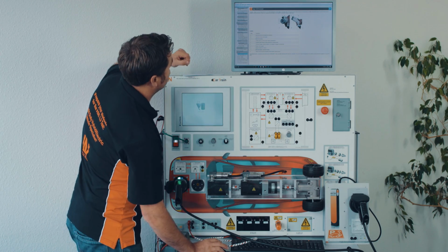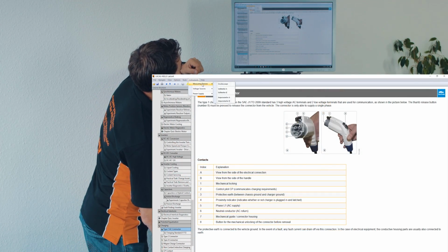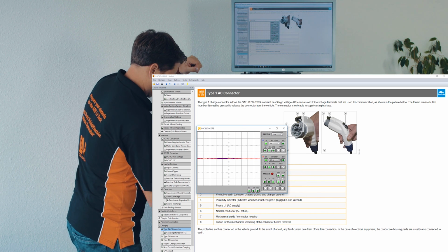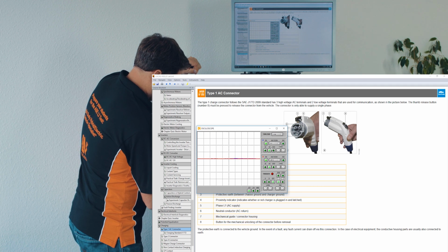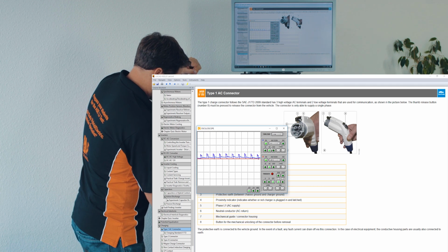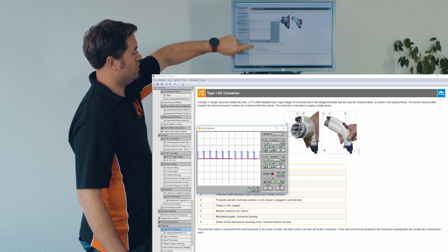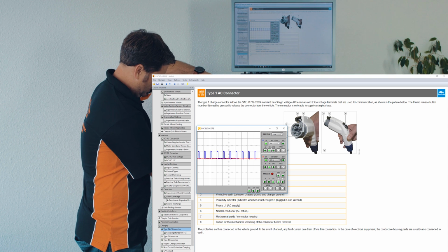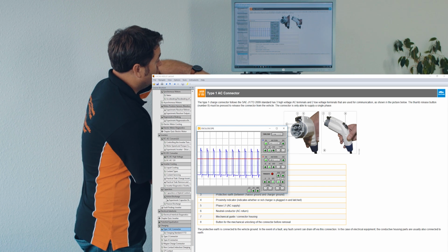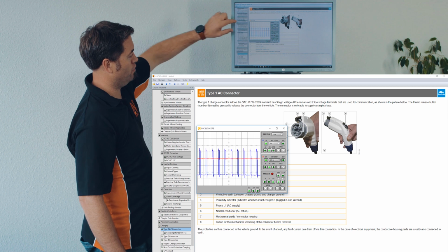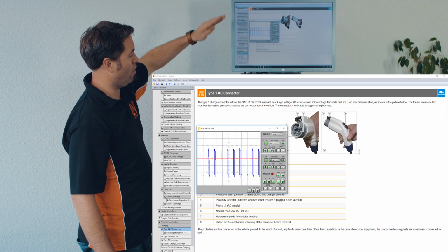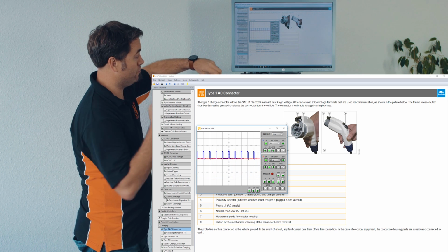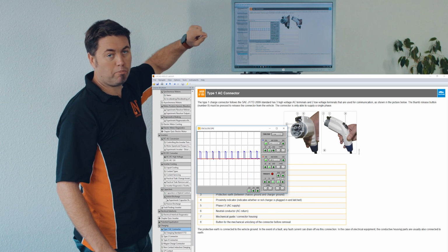But just to show some of the communication that's occurring. Here we see the pulse width modulated signal that the car is reading. And this is what the vehicle is reading. So we're seeing here bipolar, it's on both sides. Within the vehicle itself, that is the same signal, but it's being rectified.